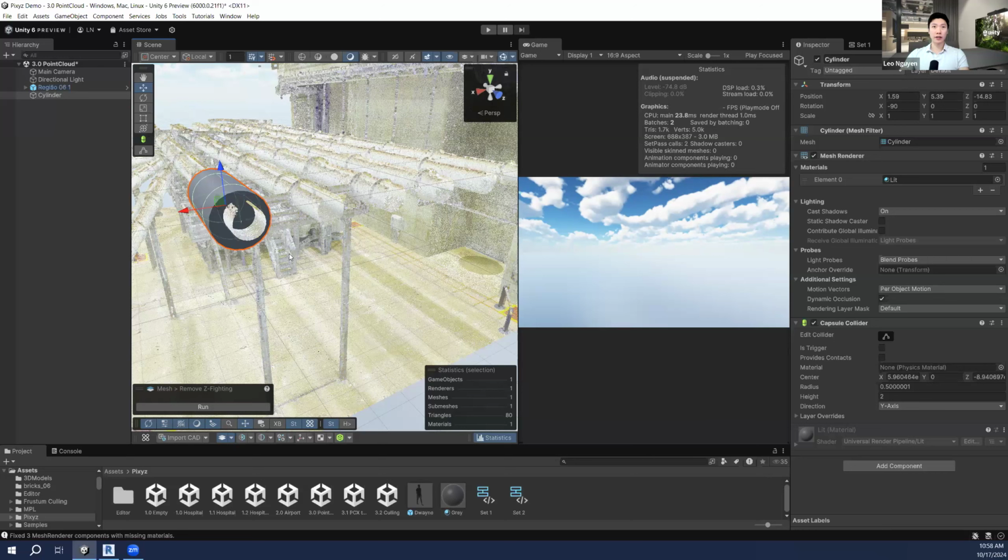Essentially, you could take a DWG and convert it into an SVG. That will give you additional lines and edges that you can work with. And then in ProBuilder, I believe you can probably select the lines and create a polygon from those edges. So yeah, let us take a look at that and see if that would be possible.